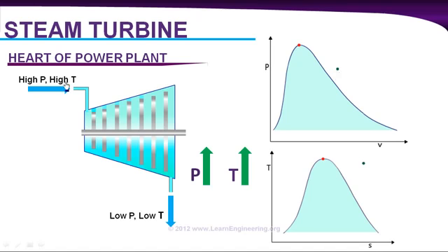During this process, we know pressure decreases. So in the pressure-volume graph, the pressure will come down. Since this is in a gaseous state, obviously the volume will increase with the decrease of pressure. So this will be the curve. It's an adiabatic process. In the temperature-entropy graph, temperature is coming down during this process, and there is no heat addition or heat absorption to the fluid, so this is a constant entropy process. So you can draw it like this: temperature is coming down and entropy is constant.